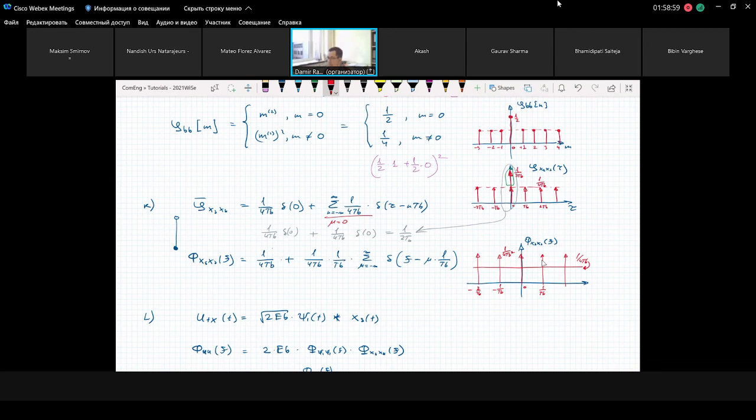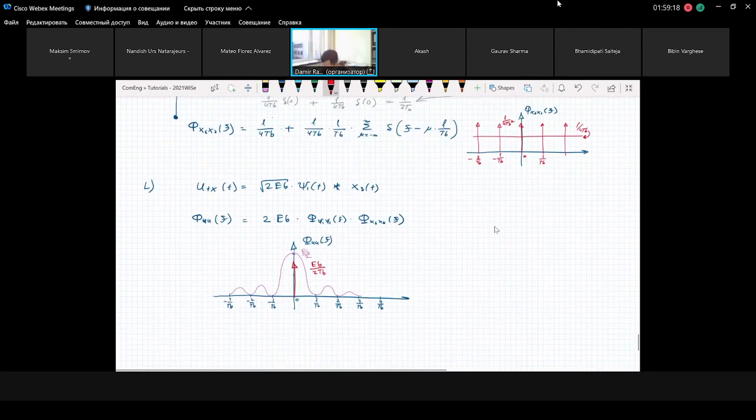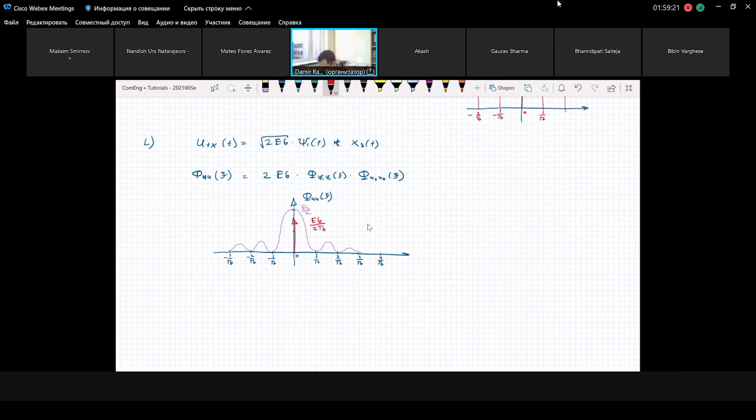For this reason, it's not good to say that impulses are below the DC level or the DC level is above, because impulses just go to plus infinity or minus infinity. I hope it's clear. We just need to denote somewhere with an arrow that it's a delta pulse, and it goes to plus infinity, but it has finite area under the curve. So we get these two parts: the continuous part and the delta pulse.